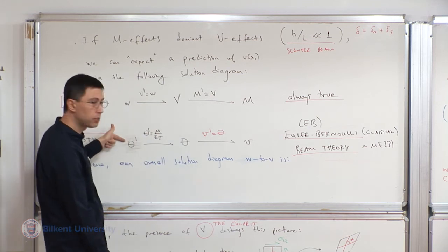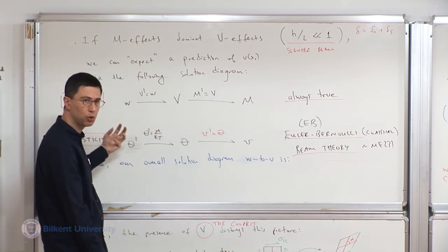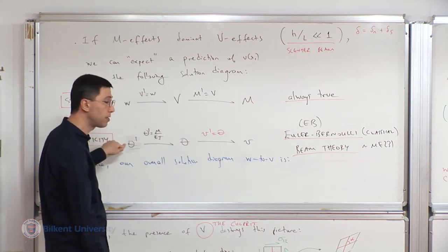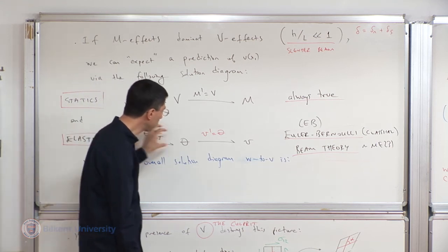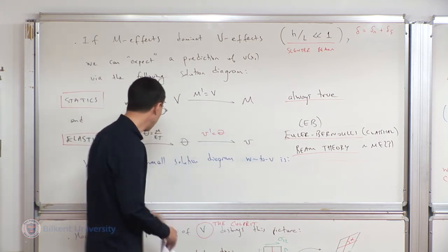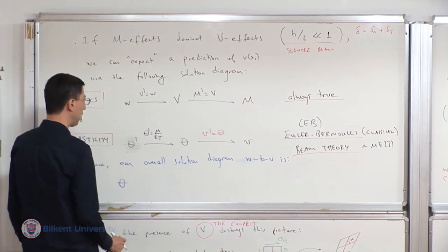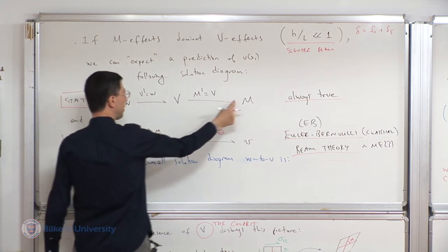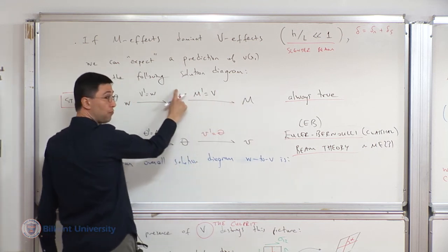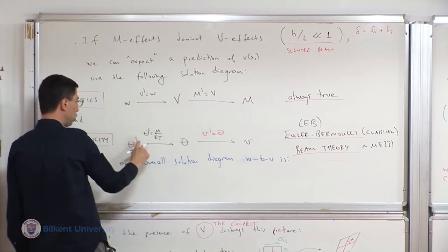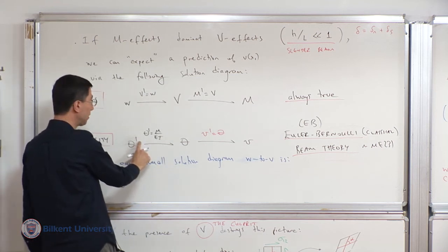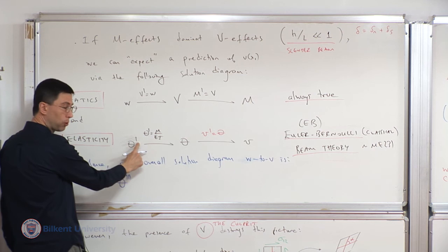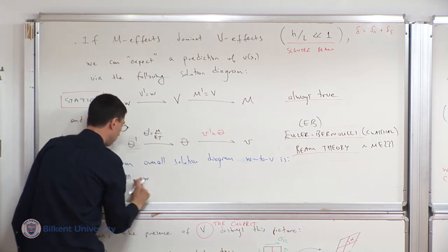But in the middle appears this quantity theta. So I like to rephrase everything in terms of theta. So I like to think that somehow given W, I work with this quantity theta that represents rotation. And from rotation, I make a transition eventually to deflection. So I'd like to start with theta. But the starting point is originally W. But now if you look, you see there is an M here. If I take one derivative of M, I go to V. Another derivative, I go to W, which means if I take two derivatives of theta, I can make a connection to W. And indeed, the third derivative, two more derivatives, is equal to W over EI.